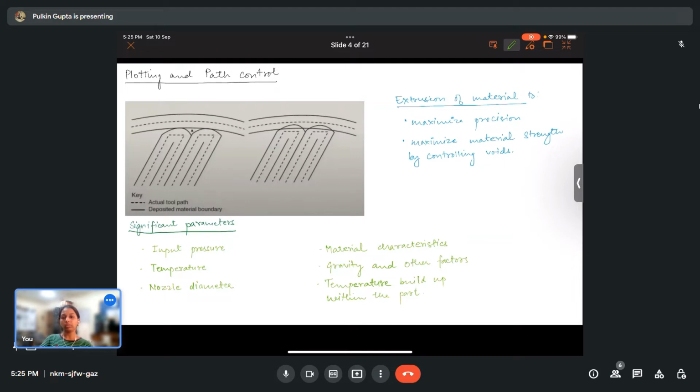Will it be completely solid, or will only 50% of the space be occupied with material, or just 10%, which is known as the infill density. Okay, and this information is really crucial as it determines the strength and the mechanical properties as well.